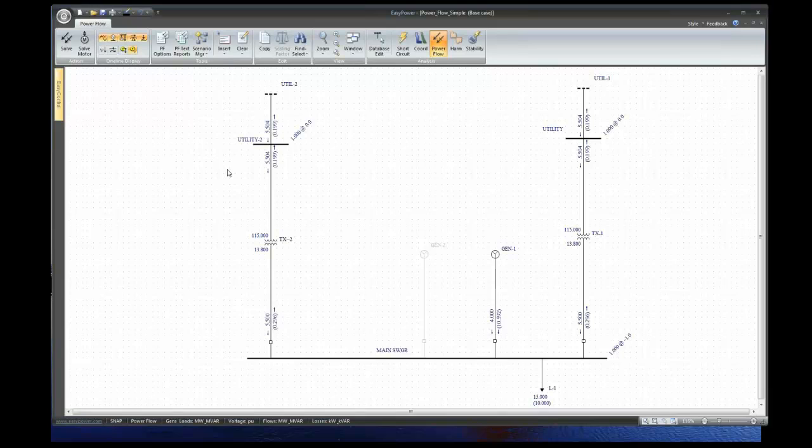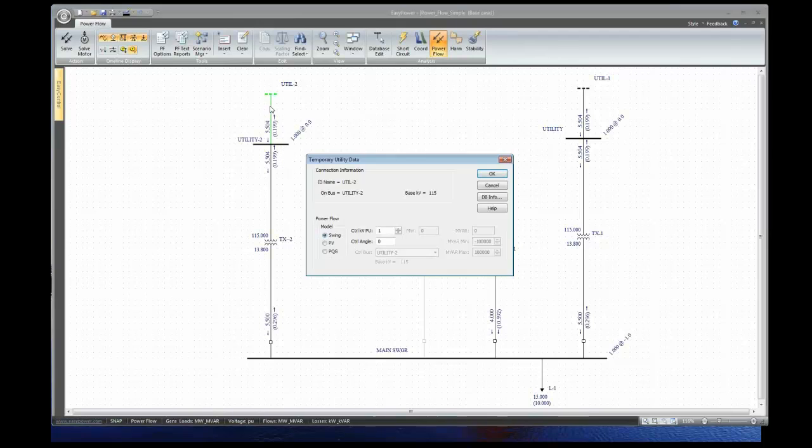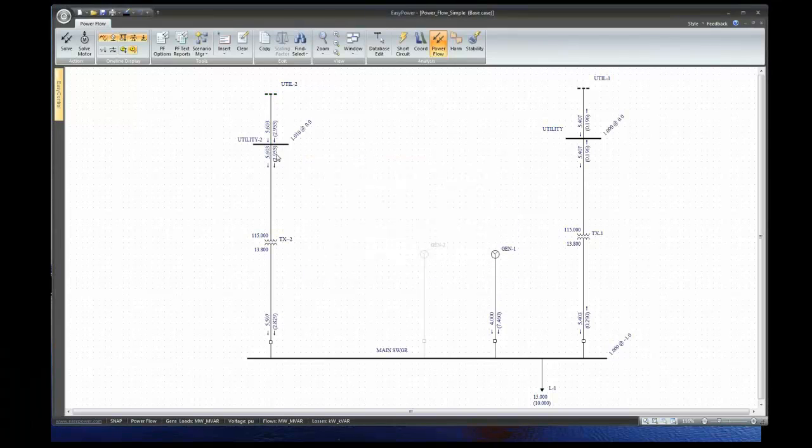So we talked about the kW not being a function of the voltage. The VAR flow is going to be set by the voltage. So if I were to come into this source and say that it's going to be 1.01 and this is 1.0, now I get much more VAR flow coming from the higher voltage, and I take a little bit less from the generator. Okay.